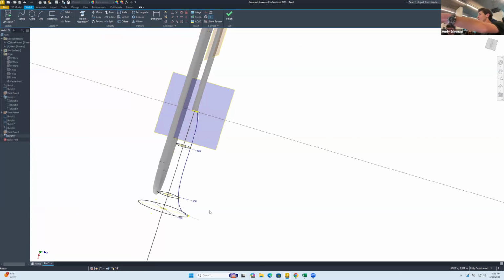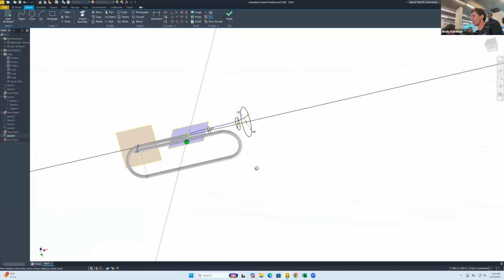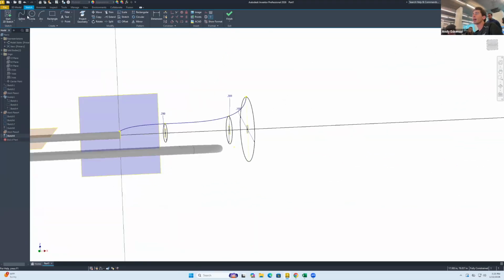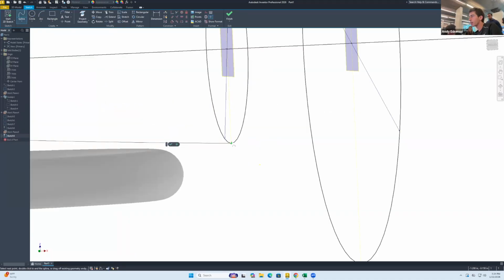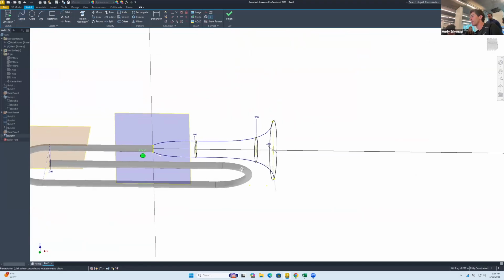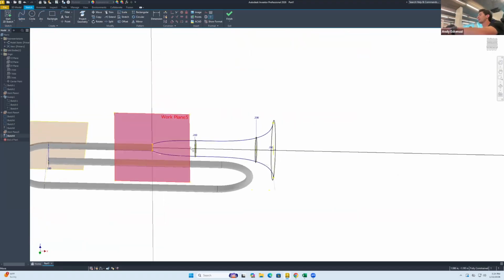So you see how there's potential to improve this design a little bit more. In fact, I might change some of that, but let's try this for now. And let's do another spline. So let me add this one in here. Is that, yes. And there. By the way, because this spline is fully defined by those lines in there, if I change the diameter of that circle as an example, everything else should modify accordingly.